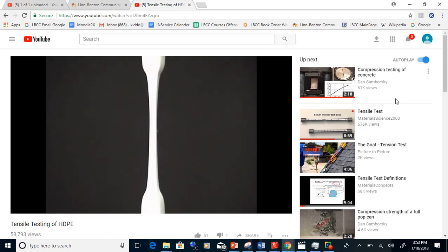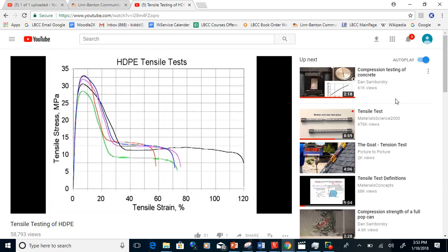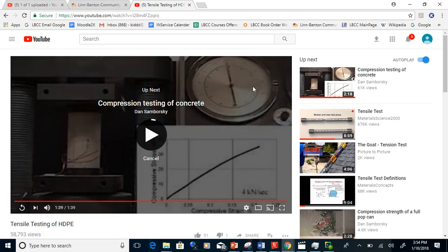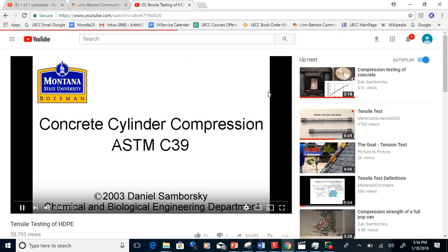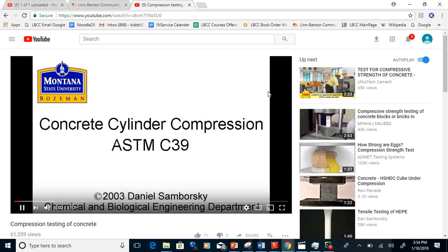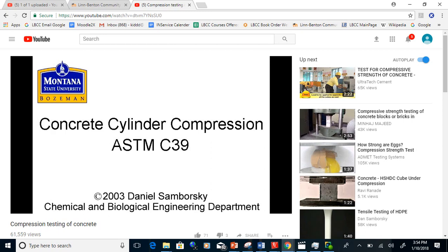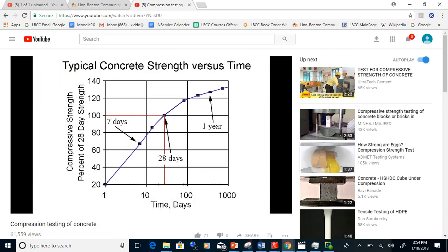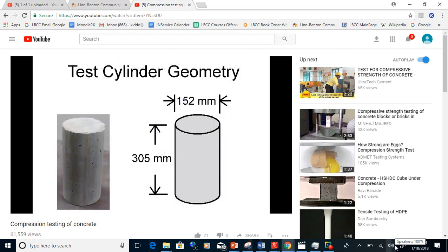Just because the machine is pulling it and it looks like it's stretching doesn't necessarily mean the material itself is that soft. If you took it out of the machine, you wouldn't be able to just bend it easily. It still holds. It's just a very strong machine, hydraulically driven. You would have undergone so much strain hardening at that point. Have you ever tried to break a paper clip? You get to a point where you can almost not do it. That's strain hardening. I always break my paper clips. So, it depends.